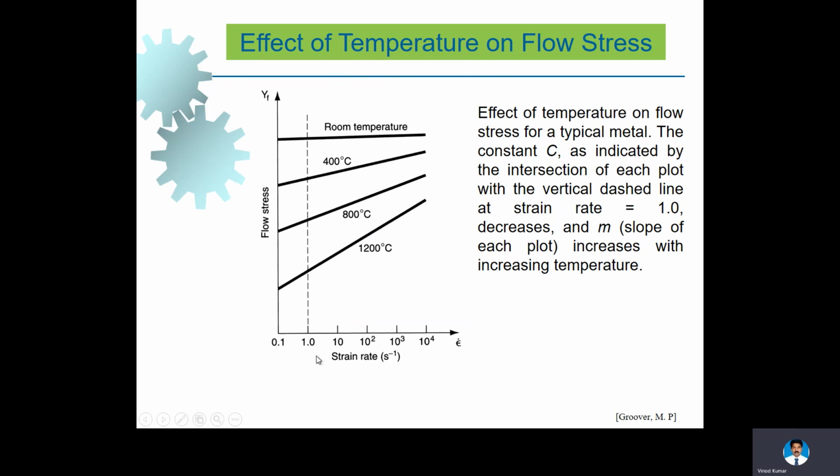If you take 800 degrees, and you want to increase the strain rate, definitely more flow stress is required. Now, the effect of temperature on flow stress: as you can see here, at higher temperature you need less stress to deform. So this is the effect.